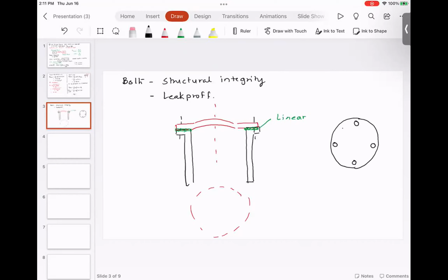If you start drilling another hole over here, and another, what's going to happen is there will be a region where, even though you don't anticipate it, there will be deformation. And that deformation, rather than sealing the joint, would give you a weak section where the gases can escape.